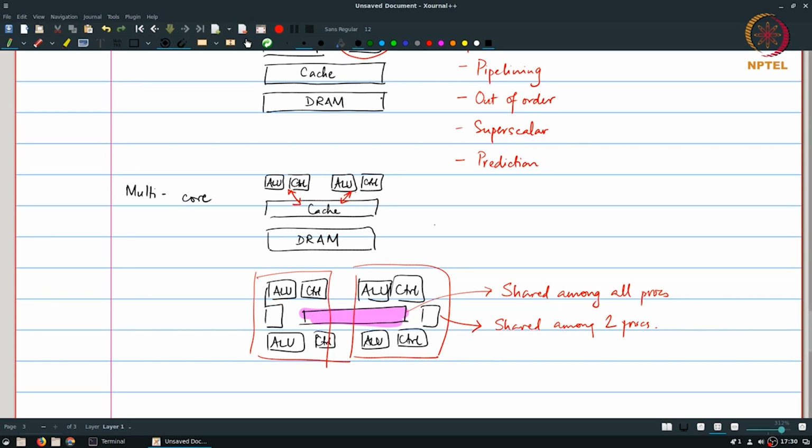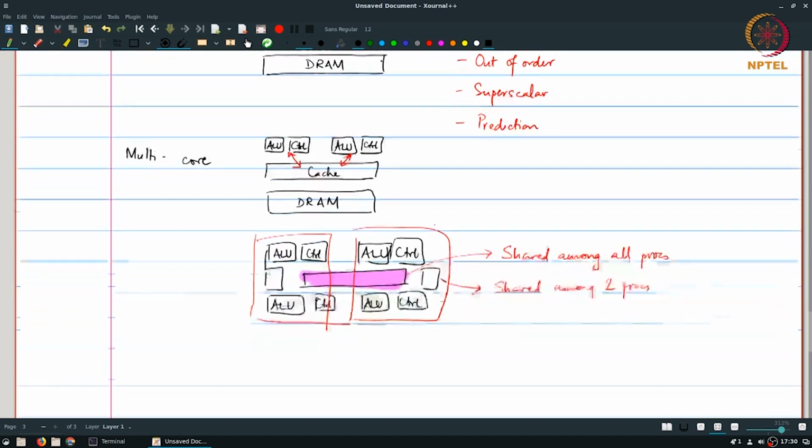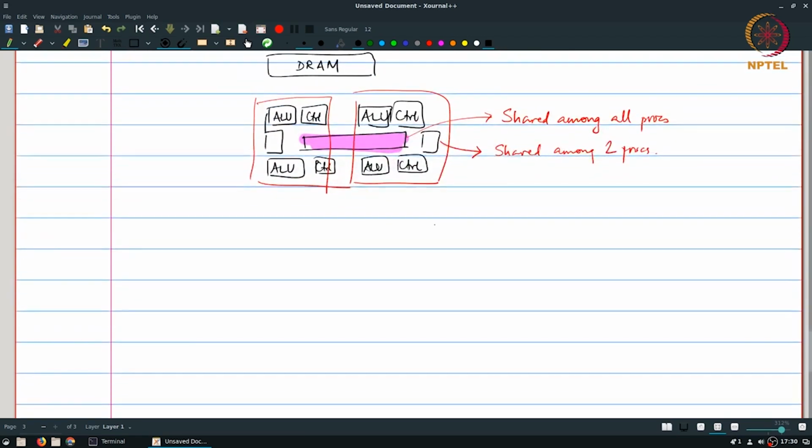Now, of course, the problem that you can see over here is the control logic is still quite large and complicated and consumes a significant amount of power. The observation that the architects of GPUs made was that for the most part, while talking about images, you could actually think of each pixel or each small block, maybe a 2x2 or a 4x4 block of pixels inside an image, as a separate unit for the computation. And if it was in some way possible to have one processor dedicated to each of those pixels or each of those small blocks, you could potentially get an extremely high level of performance out of the entire system.